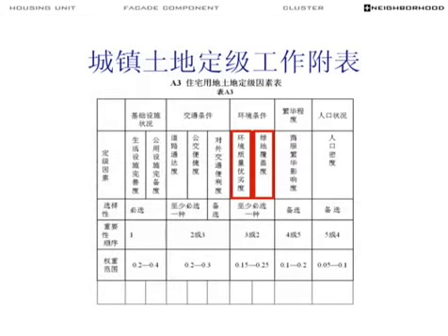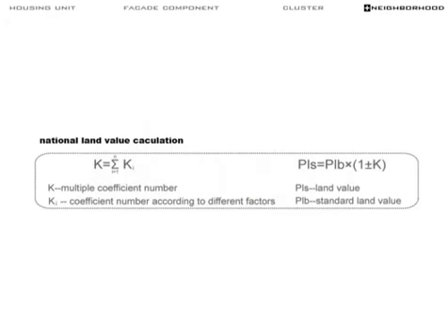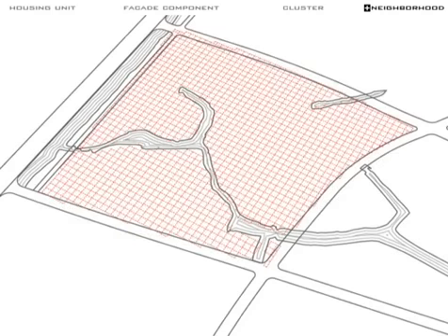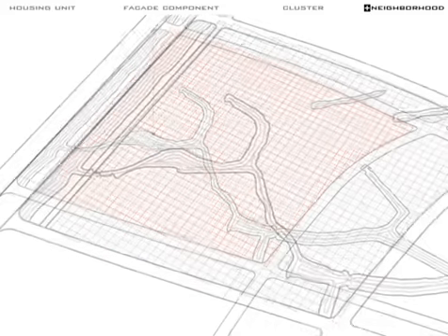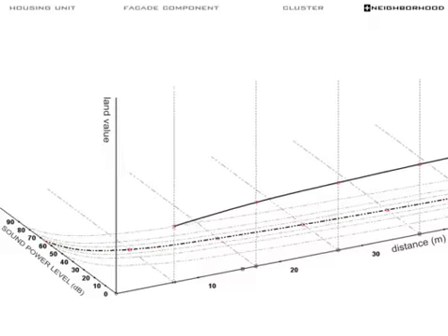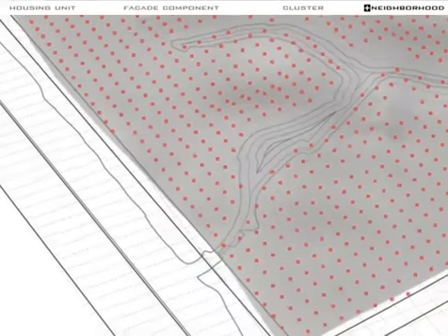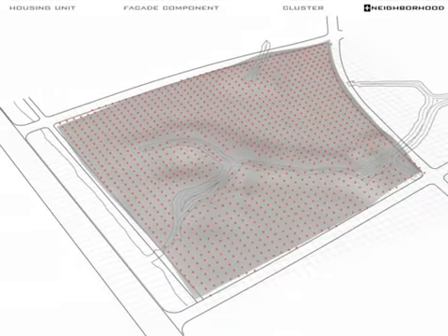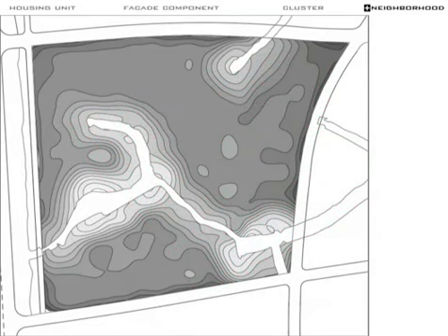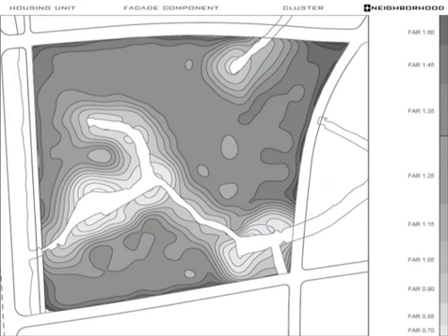Following the economic principle, 2 driving factors of land evaluation are considered to differentiate the site in this scale: the noise and water landscape value. A 10x10 grid is positioned on site. Each intersection point needs to be calculated according to the graph of sound power level and the distance towards the water based on the river width. As a result, the outcome points are differentiated depending on the position where they are located. A land value map is generated. Each gradient of grade relates to different FAR value, income group, family structure, housing arrangement, and numbers of neighbors.